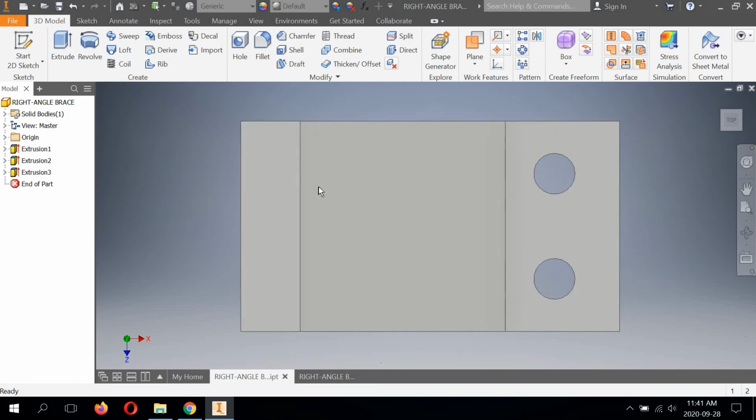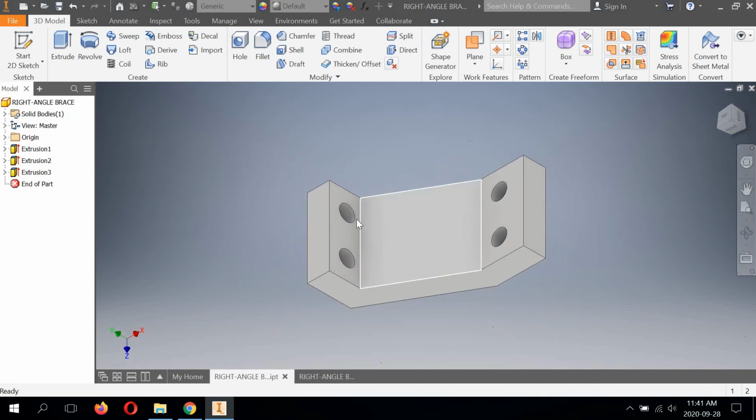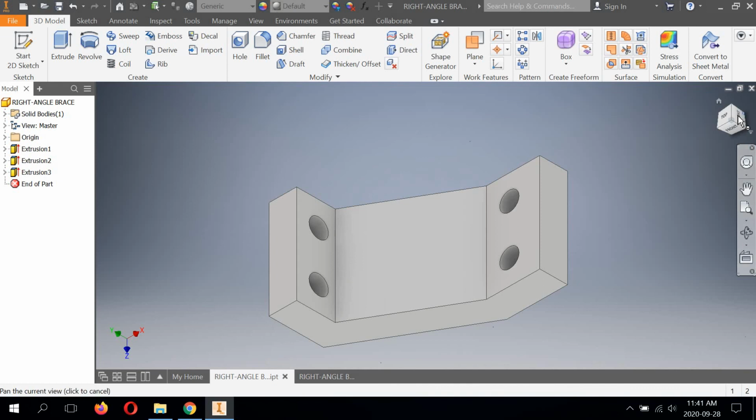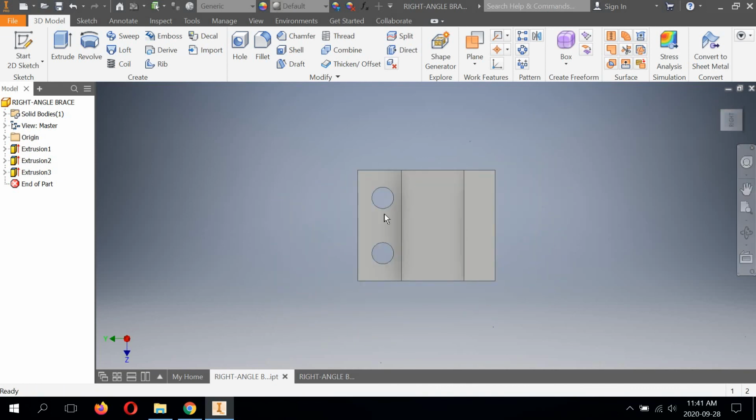But a drawing file will reveal things that we typically can't see by our naked eye. We have to show them with dashed lines that are called hidden detail lines. And those are round, so they require a center line. So if I go back to ISO view, right, you can clearly see those circles and how they pass through the back of the part.